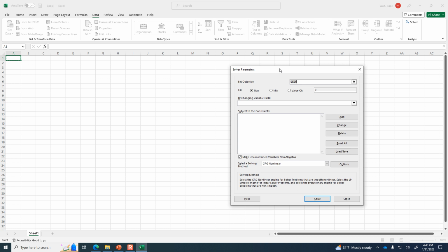I drew it on the curve before, on the whiteboard, as something looking like this. For flow rate increasing, what we want to do is have the maximum amount of money. So the more flow rate you've got, you can sell more electricity, but then you're going to get to a certain point where, because the head losses get more and more extreme with higher and higher flow rates, you're actually going to be losing energy through the pipe.